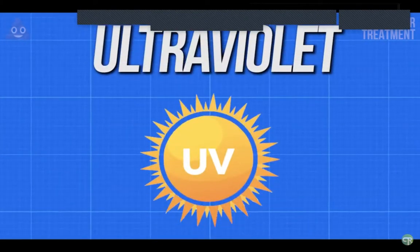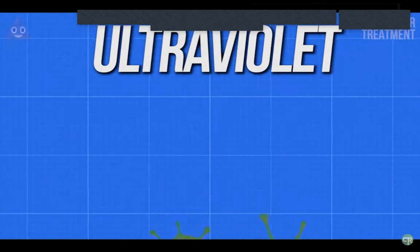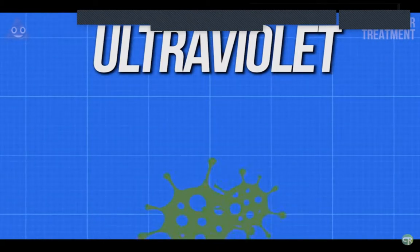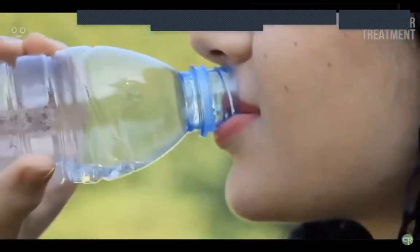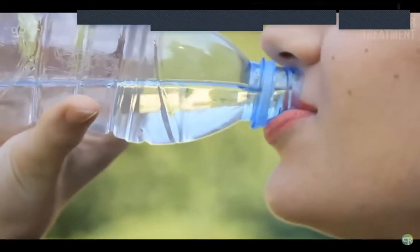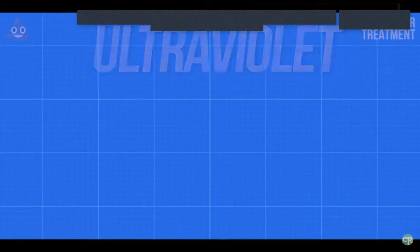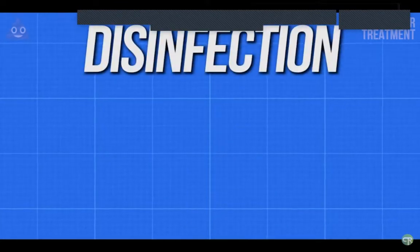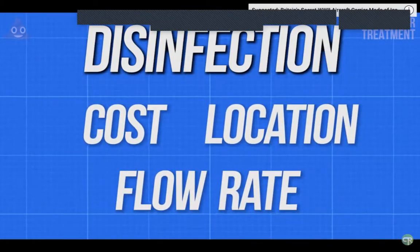The last common method uses ultraviolet light to scramble bacteria's DNA so that they cannot multiply. In UV disinfection, the bacteria in the water aren't killed, rather they're sterilized, rendering them harmless. If you were to ingest water with living microbes immediately following UV treatment, any harmful bacteria would be unable to multiply or render your body damage. Engineers choose between these methods based on a variety of factors such as flow rates, cost, and location of discharge, which brings us to the final step, effluent release.